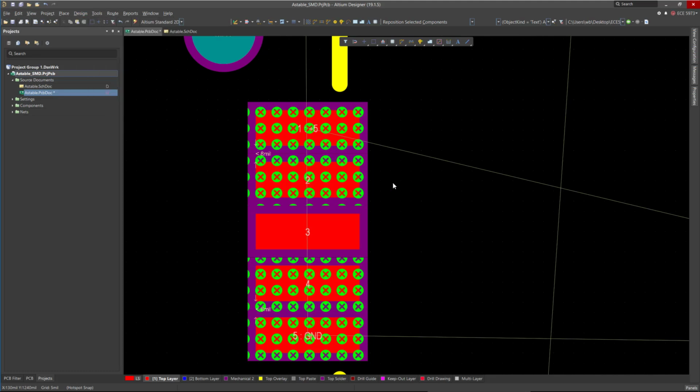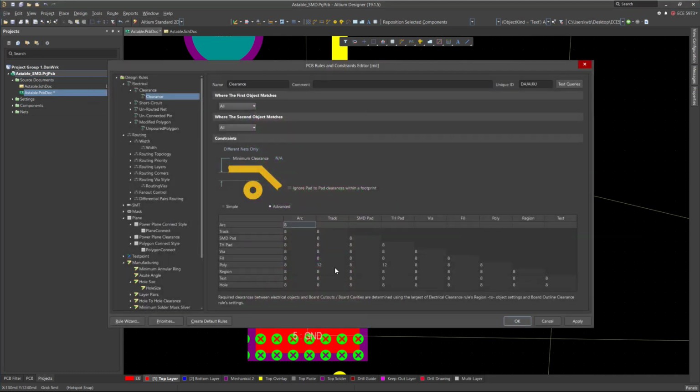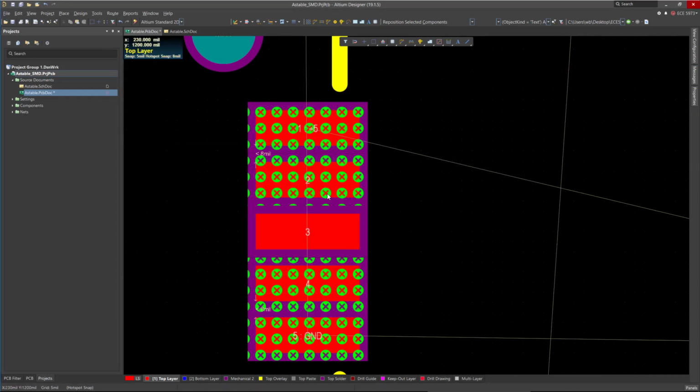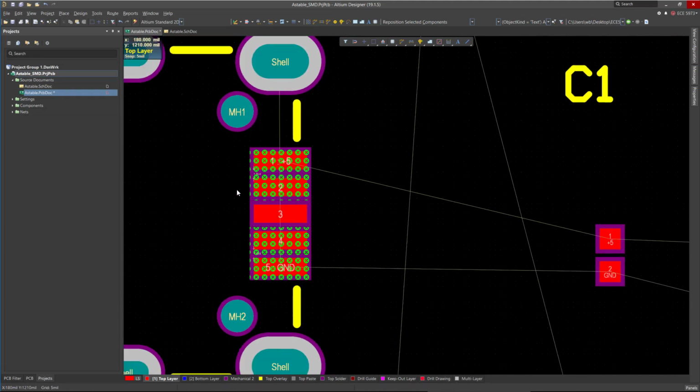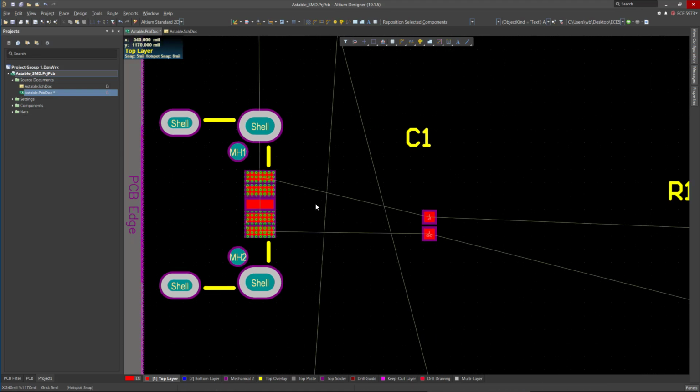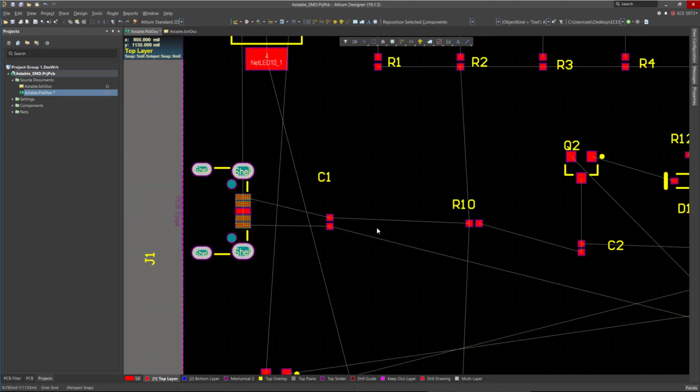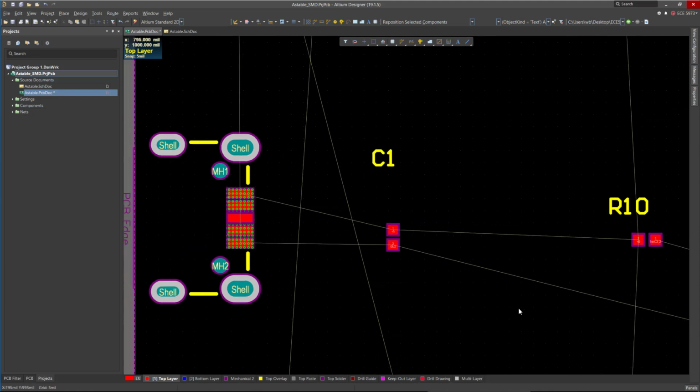So they have not yet changed. Now, when it comes to surface mount components, the pitch between the two pins becomes much smaller, and the clearance between the two also becomes much smaller. So you need to specify the design rule according to the components you are using, based on the spacing, the pitch of the component, and so on. We can change this in a bit.